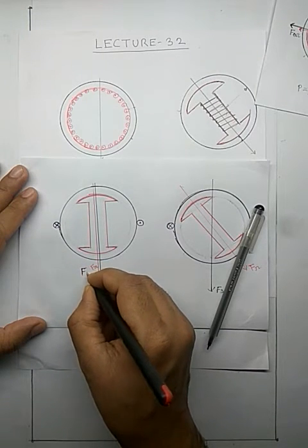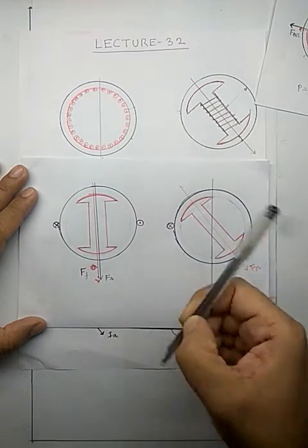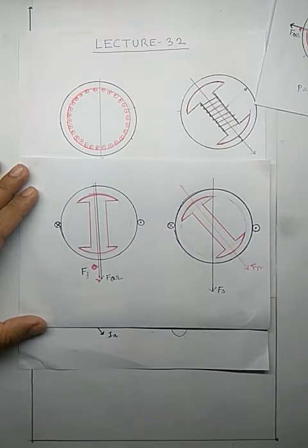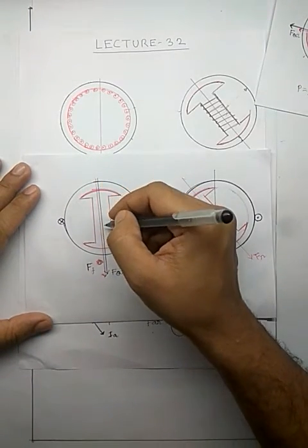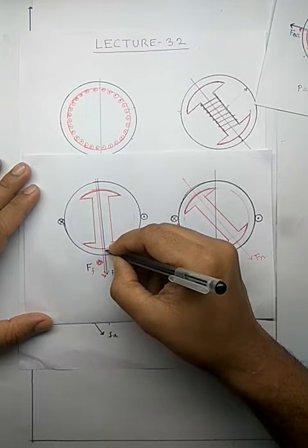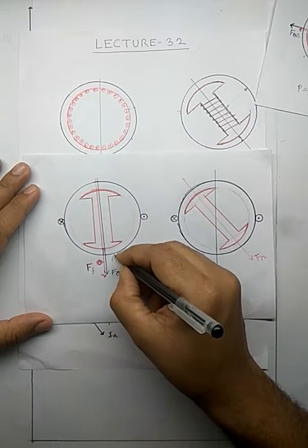Let this be phi f, the flux produced by the rotor, and this is the flux produced by the stator, let's call it phi AR. The air gap through which this rotor flux and stator flux flow is the same here. Let's say that the reluctance here is R1.